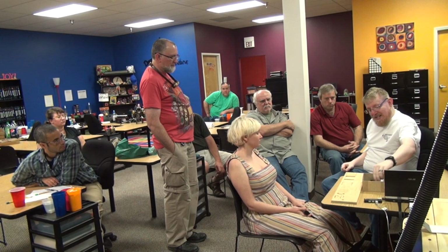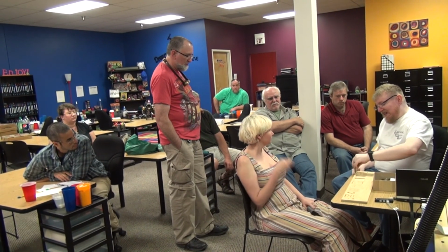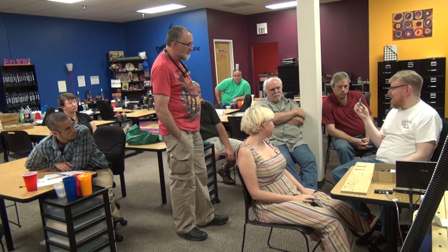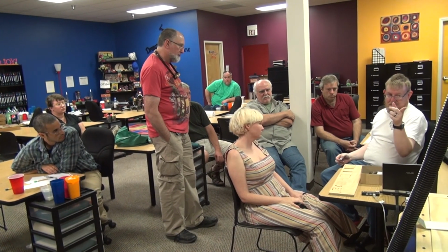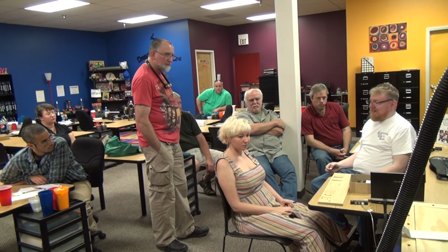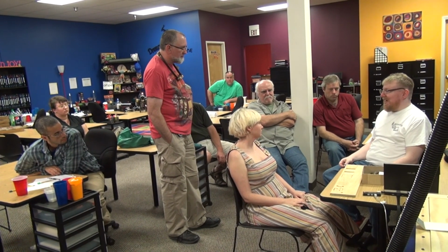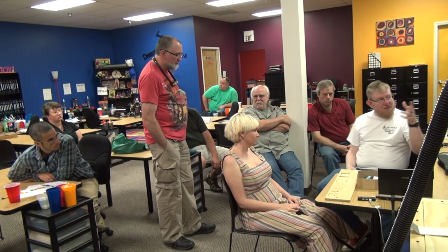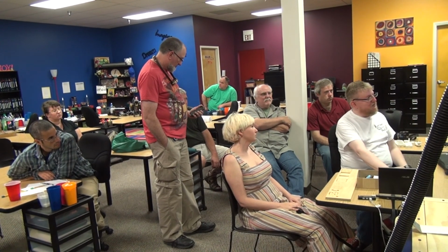So the direction that you take your bit around this, I'm either going to go clockwise or counterclockwise depending on which way the cutter on the bit is. And this one only goes in one direction, but I do think they even make advanced spindles that you can go either way. So if you had a need, you could do that, or special bits or whatever. So you pretty much leave it as climb cuts and go in the right direction, you'd be fine.